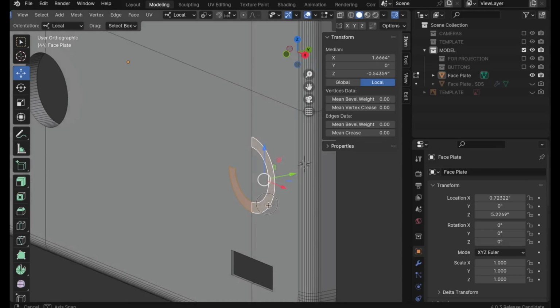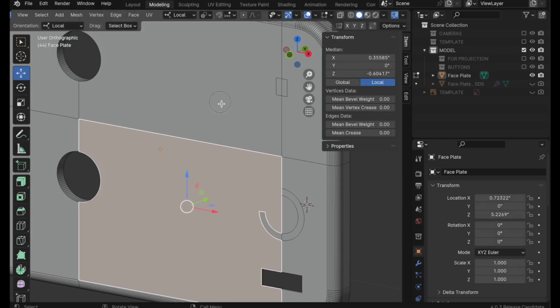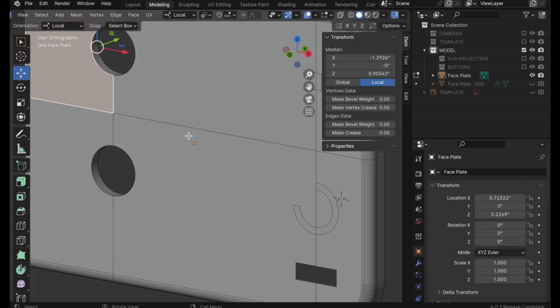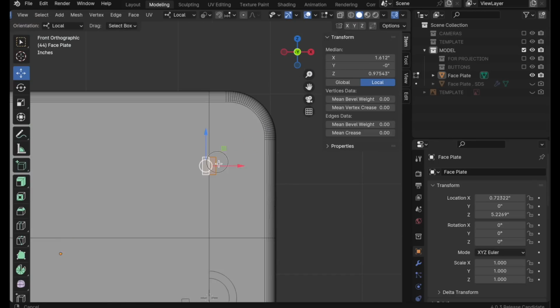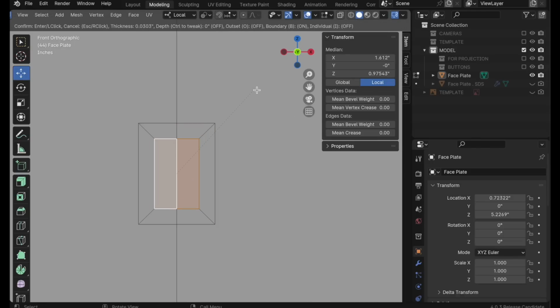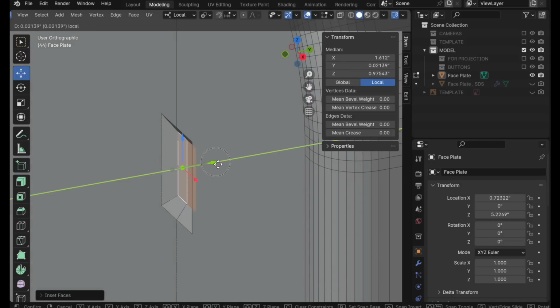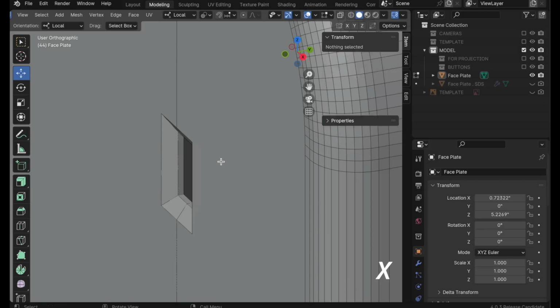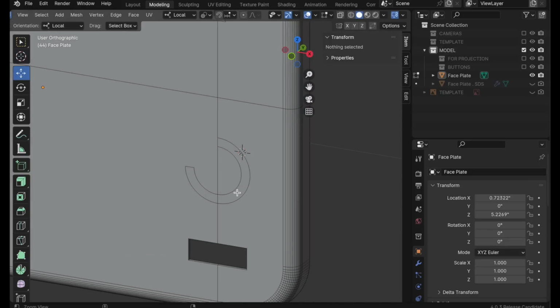Those are polygons, believe it or not, and all of these are just large ngons, and we don't need to worry about dicing this up for subdivision surfaces. Let's come up here and do the next one up here. Front view, let's zoom down. Press the I key to do this inset. Rotate around, I'll just grab that and move that in. Then E key to extrude one time, and then X key to remove those faces. There we go. And then let's come over here.